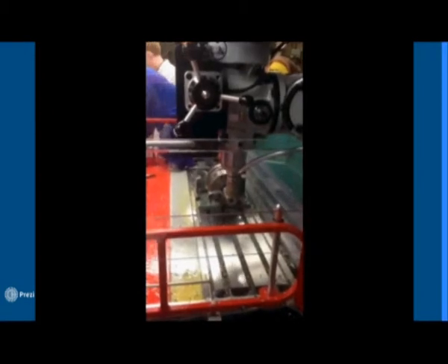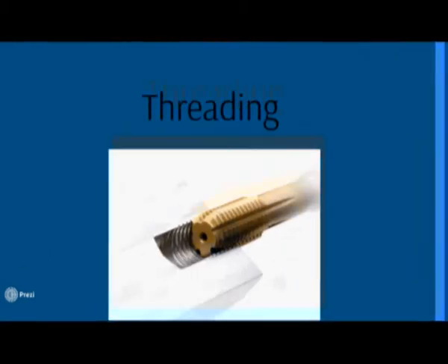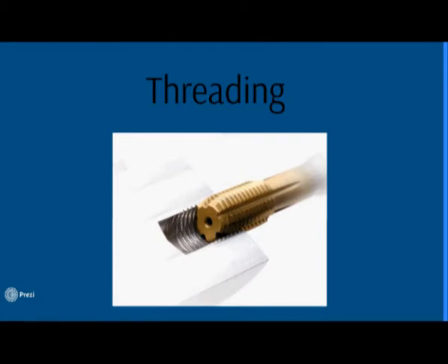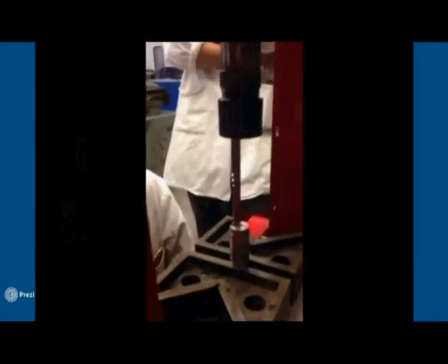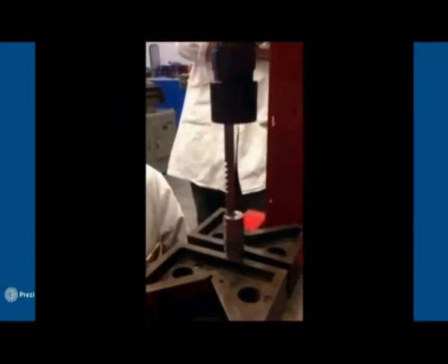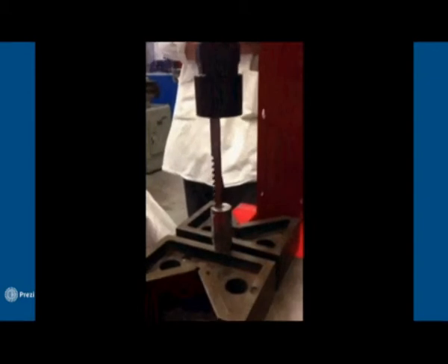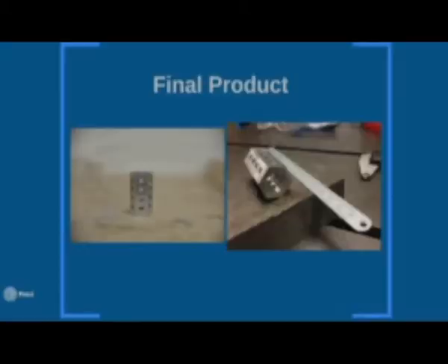surfaces of the hub. To accommodate the grub screw, a threaded hole is required in the hub, and this is done by putting a tapping drill through the hub using a tap wrench. Finally, the keyway for the hub is created by using a broach, which is basically a multi-pointed cutting tool. The broach is then pushed through the hub by using a hydraulic press to create a keyway.